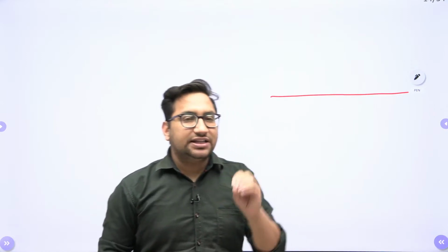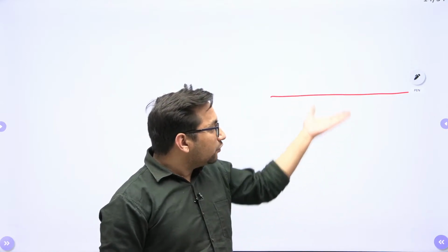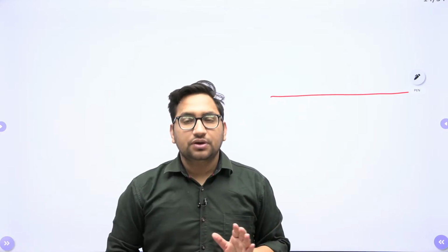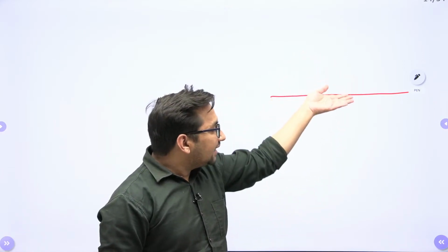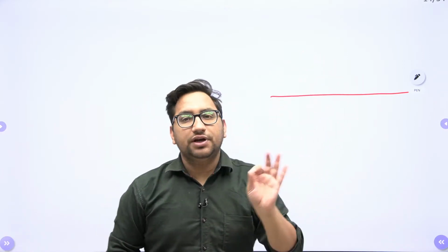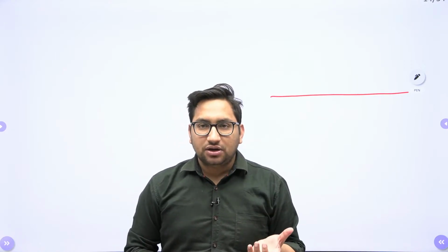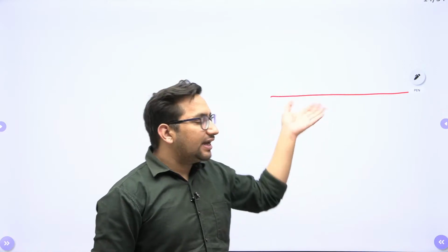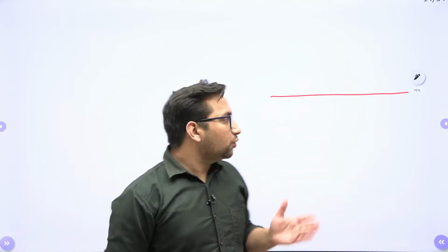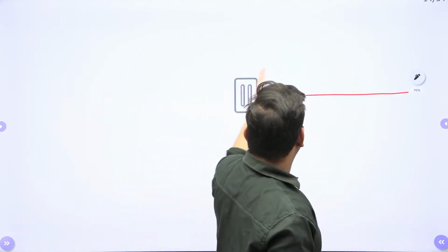It means to get that particular minimum value, you have to fail this soil. You have to apply the load on this particular soil up to the failure. Now for that, a very heavy load will be required. Also your soil at this particular level will fail.